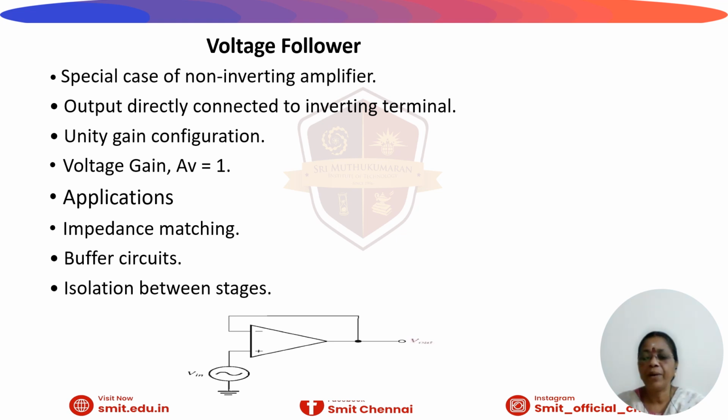It has high input impedance and low output impedance. It is used to isolate a high impedance signal source, for example a piezoelectric sensor or pH probe, from a low impedance load, to prevent signal distortion. It also protects sensitive, weak signal sources from being loaded down, and is frequently used in circuit design to maintain signal integrity. Thus, it offers major advantages in these applications.